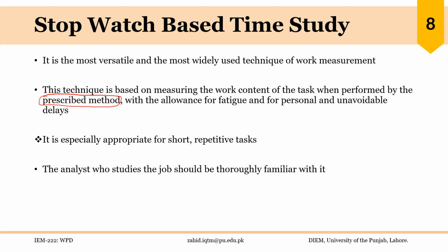We can actually use time study before standardizing the task if the goal is to improve the task. But if you are going to set standards for performance, then you should first improve the task using the approach that we have already discussed and then find its standard time. So stopwatch-based time study is especially important for short, repetitive tasks, the tasks that are performed over and over again by the worker. The analyst who studies the job should be thoroughly familiar with it. So this is also a very important consideration.